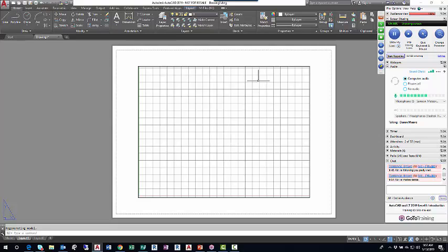So it's this viewport that allows us to take designs of residential and commercial sized buildings and shrink them down to fit on 8.5 by 11 or 24 by 36-inch paper. The viewport is scalable, so we'll work on that. I'll just show you how to configure your viewport to show your drawing, so that there isn't a ton of work that gets done in layout space for the most part.